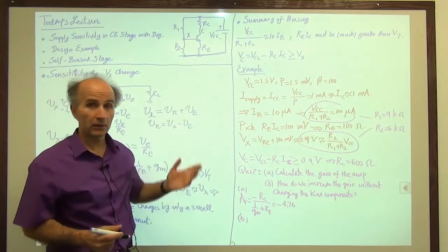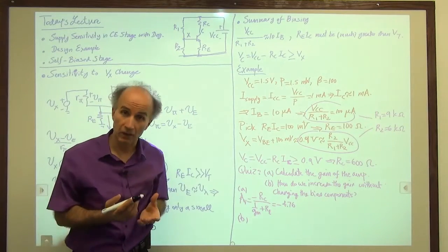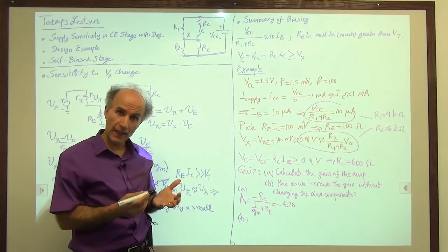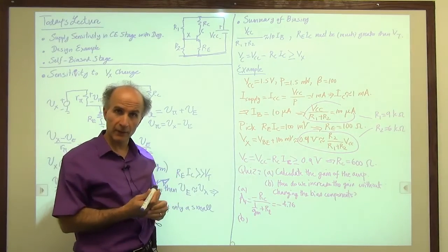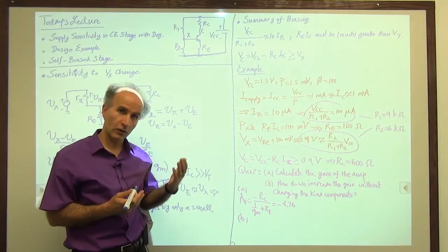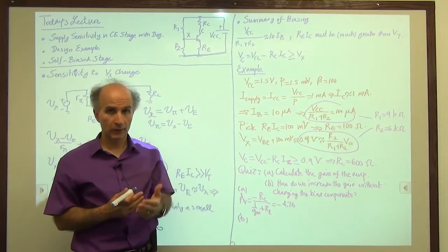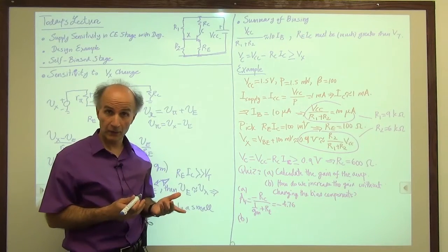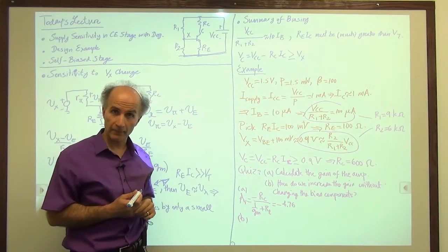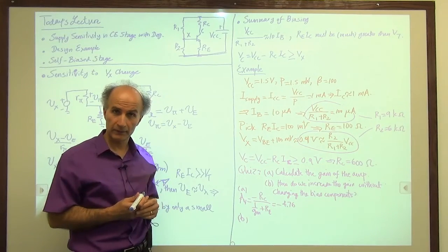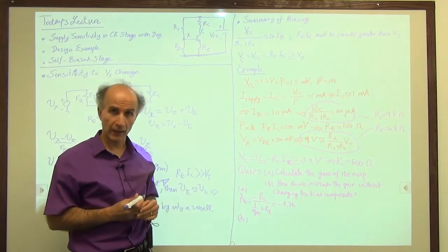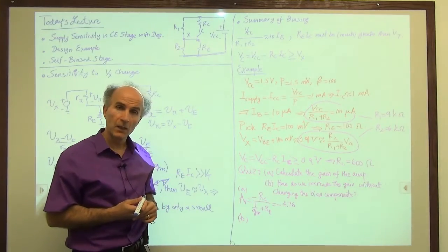This amplifier is used to amplify a signal, right? And the signal has some frequency content in it, some frequency components. For example, human voice has a range of 20 hertz to 20 kilohertz. If you have a video signal, the video signal that this camera is capturing right now has about 5 megahertz of bandwidth. Goes up to 5 megahertz. Well, this is a high definition camera, so maybe a little more.